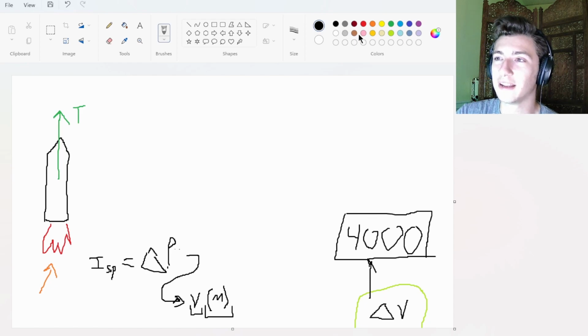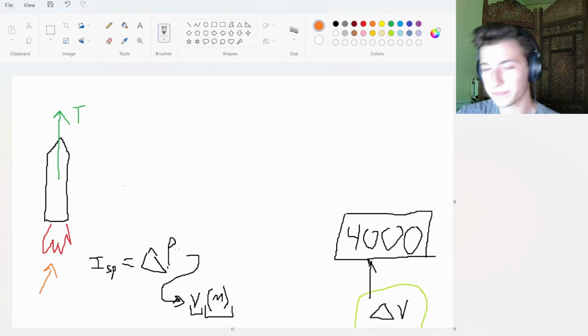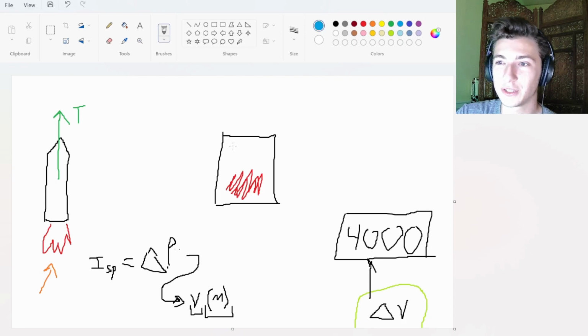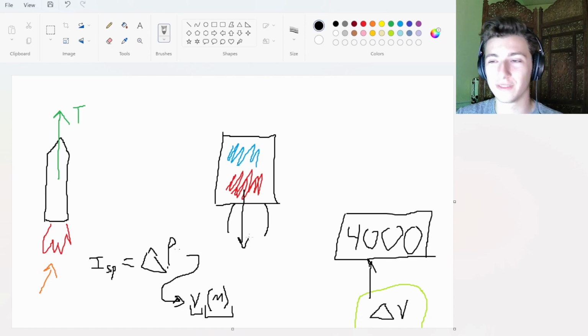get into orbit. Now the way that you design rockets most efficiently, not only in Kerbal Space Program 2, but in real life, is using stages. So say we have this rocket engine, right? This is our rocket engine. And we have this much fuel, which is the, say, methane in methalox. And then we have this much oxidizer, which is the oxygen. And then we have our actual nozzle down here. So what happens is, and again, this is super simplified. It's not actually like this, but the oxidizer and the fuel are mixed, and they combust, and the exhaust gases are pushed outward of the nozzle, and that is what produces the thrust.